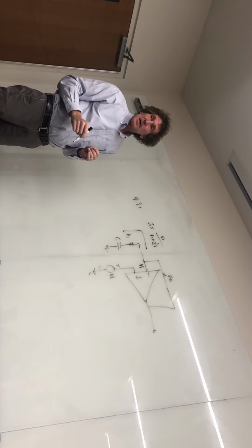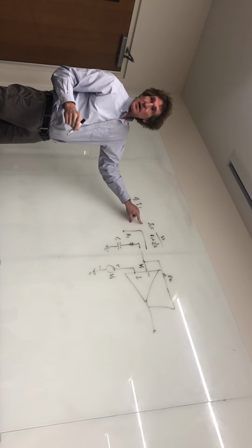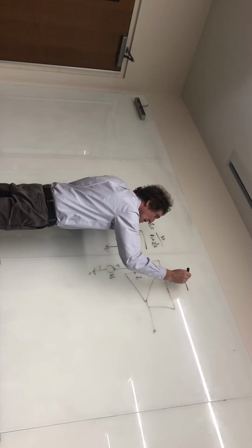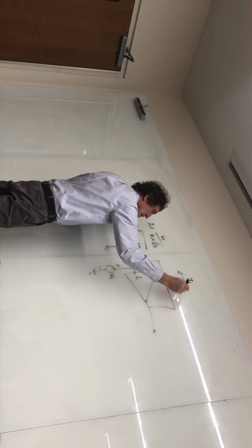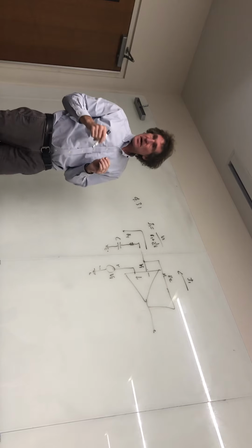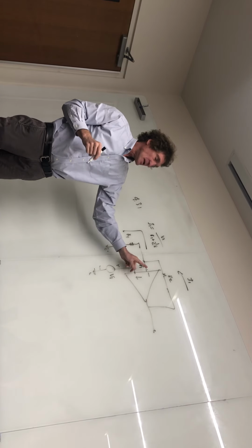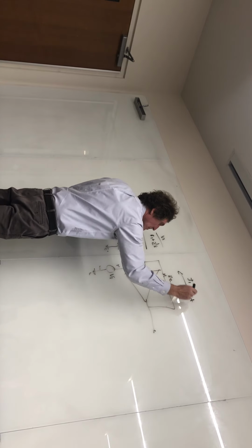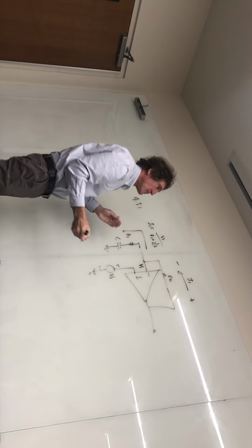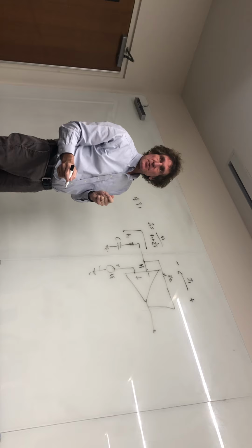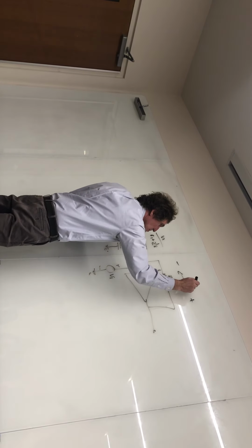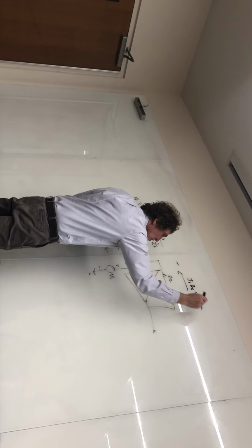Now, we have this basic thing, and I know I1 is that, correct, class? Therefore, if I1 is that, I know I2 here, or really it's the same, it is I1. That's the only place that current can come from, correct, class? Nothing can come in and out of that negative terminal. Once I have this current, I know that voltage is just I1 times R2. Does everybody agree with that? That's I1 times R2 equal to VR2.